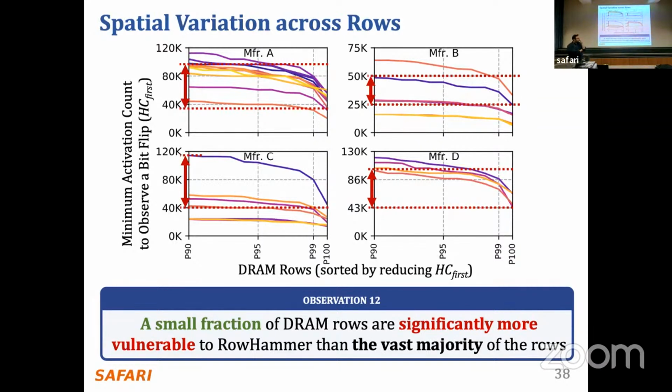We propose ECC for more vulnerable columns in particular. The reason is that when you look at a row, you have 8 kilobytes of data, right? And prior work shows that RowHammer vulnerability depends on the data pattern. By putting different data patterns in your aggressor row and victim row, you can force bit flips to occur precisely in particular locations. That is the thing that defeats ECC. So protecting the whole 8 kilobytes using ECC is hard, in my opinion.